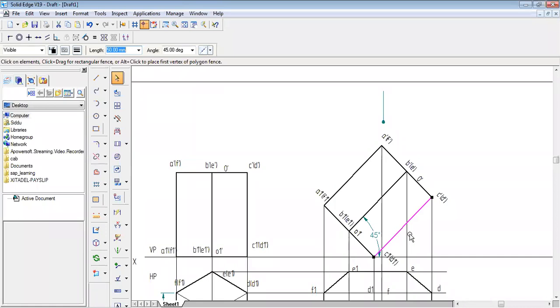So it is very, very important. Once in the first procedure you connect them with a thick line, now we have to identify seen edges and unseen edges. When I'm looking from the top, this surface is going to be seen to me very clearly. So this is A, B, C, D, E, F. That is the top view, according to the naming I'm telling. So A dash to A1 dash, F dash to F1 dash. These are the lines in the front view, but these are not actually lines, these are surfaces. In a hexagonal prism, you are going to get rectangular side surfaces.